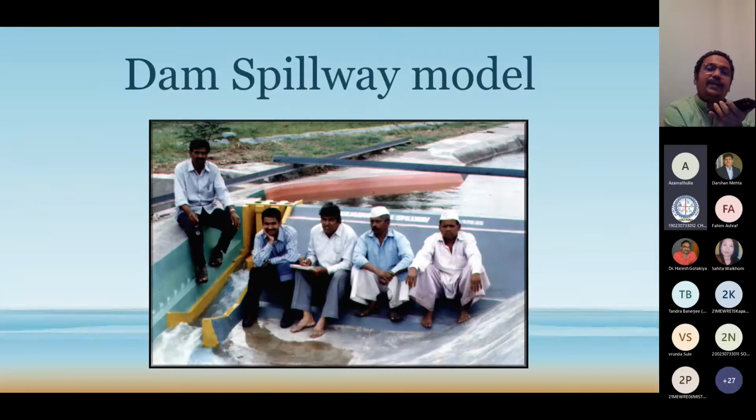is not working due to internet. This one is another dam spillway, Dhauliganga, which is my first model. This one is a 1:70 geometrically similar model. You can see this one, Rockville Dam, whether right hand side or left hand side they will provide, but here, right hand side in flow direction. Okay, this is a very long chute. You can see all these NHPC projects have breastwall type of spillways, like a small opening at the bottom like a sluice.